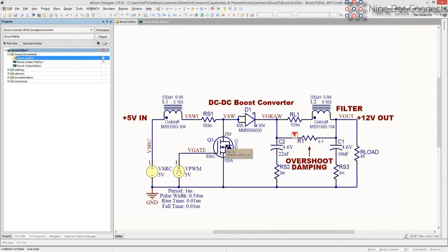Yes, you can start thinking about it. 10 megahertz, you should probably start thinking about it. One way to ask yourself a question is, what is a quarter wavelength of the highest significant frequencies involved? When your frequencies are high enough that your features are a quarter wavelength long, you have severe problems. If you stay a couple orders of magnitude away from that, you probably won't. There's lots of ways of looking at it.